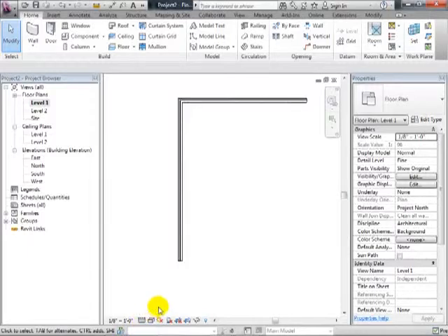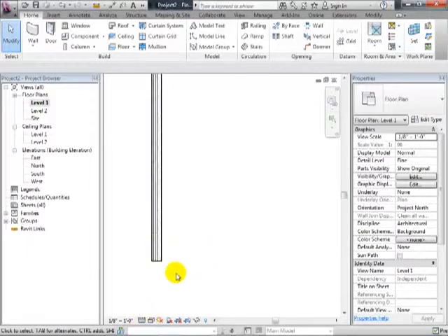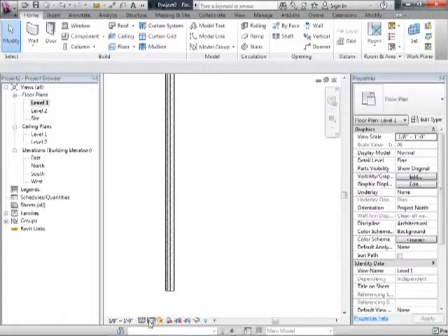Okay, which will give you a little more detail. Then you can kind of zoom in. I'm even going to go through and say shade the walls. That gives me a little color information too. But there's this whole thing about what level of detail you want to see things. Really as a matter of efficiency, what Revit's doing at a coarse level of detail is not drawing everything in incredible detail, just to make it a little bit quicker to put it out there. But at the finer level, it'll show you all that stuff.